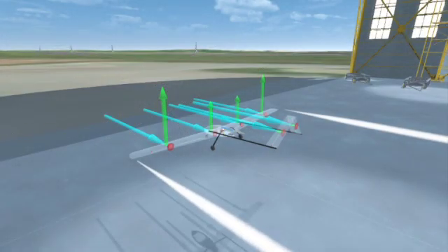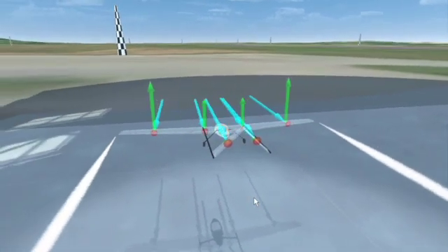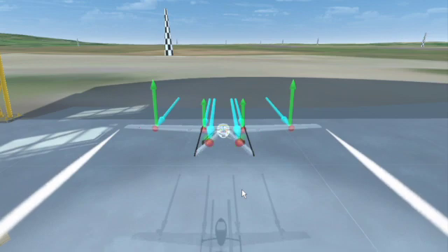An initial analysis is conducted to check the flight controls and to understand the input and output motions of the UAV. The controls can be left as they are, apart from the rudder and the flaps, which must be reversed. The rudder must be reversed to provide the correct yawing motion, and the flaps reversed to allow for the coefficient of lift to be increased. The other control surfaces can be left as they are.